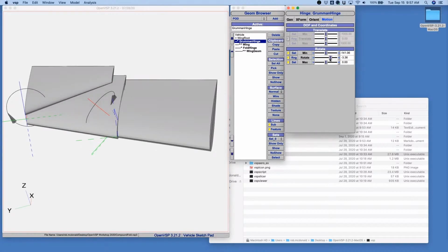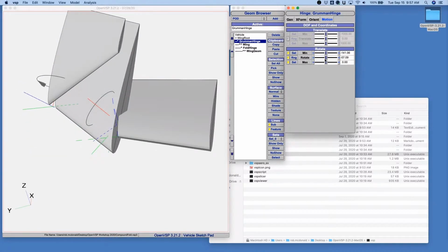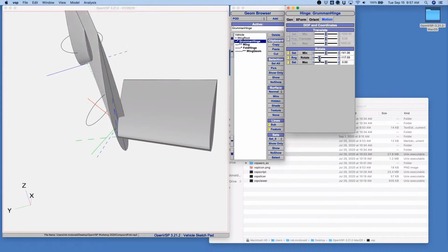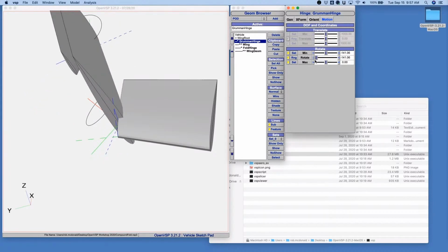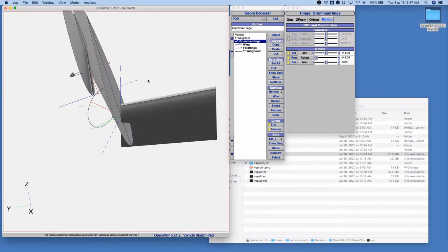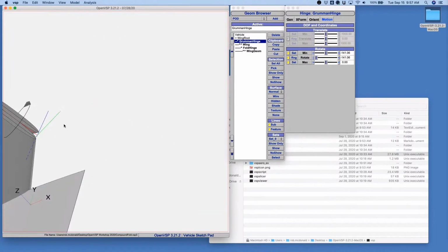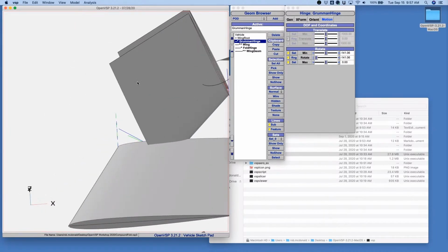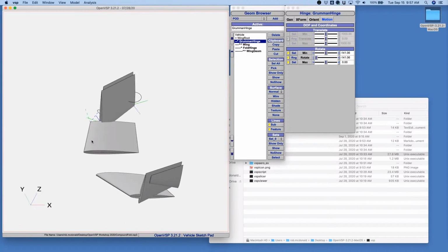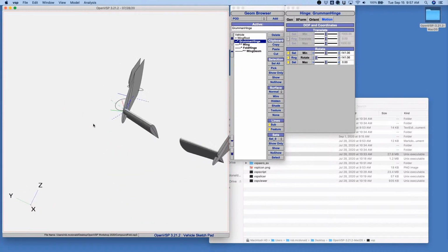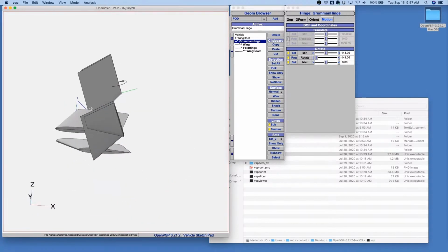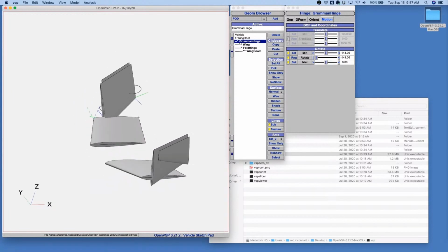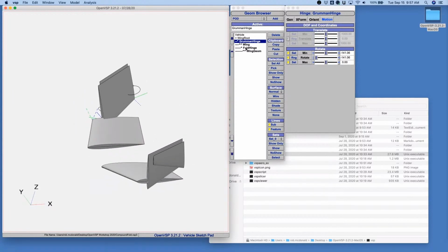As we rotate it, that tip droops down, folds back parallel, and in this case, we've folded it back along, and we've got a lot of sweep. That's why it looks a little bit different than you might be familiar, but we folded it back parallel to the body and along the aircraft. So that's using hinges and attachments in this model.